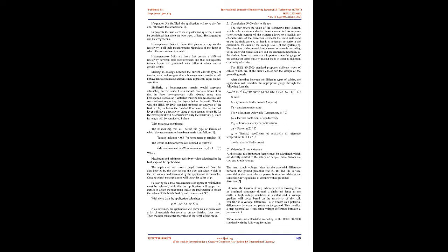As mentioned above, there are various standards to comply with this, but the one chosen for the construction of the application is the IEEE 80-2000 standard, which provides us with a methodology to design ground meshes in substations, with various formulas, graphs, tables, etc. Despite this, there are some professionals in the field who do not follow this or any other guide for the design of this protection system, that is, they do not make a preliminary study of the terrain and only assume values such as resistance, resistivities, heights, among other parameters, which can lead to inefficient work and, in the worst case, the death of those involved and mentioned above.